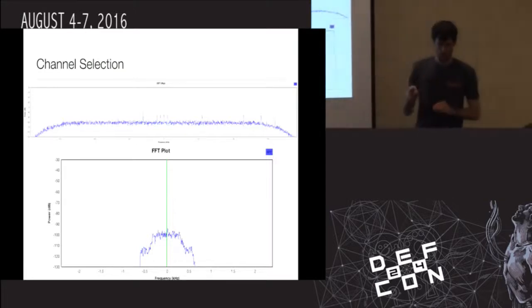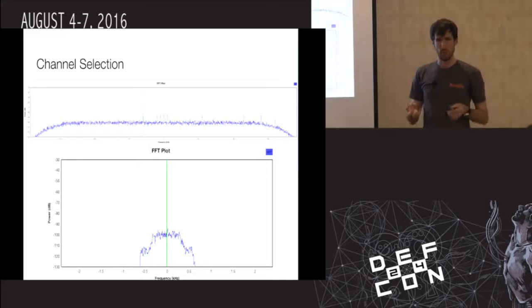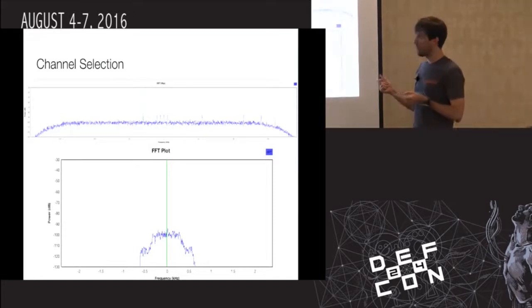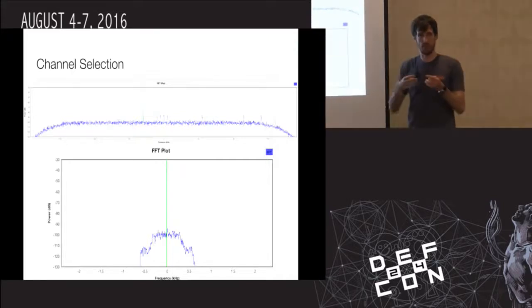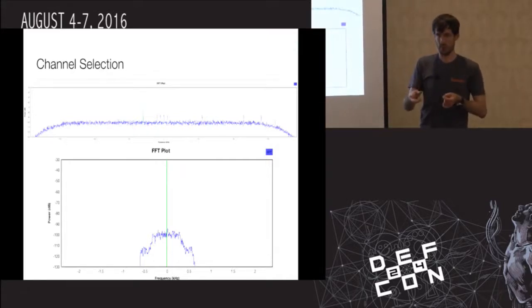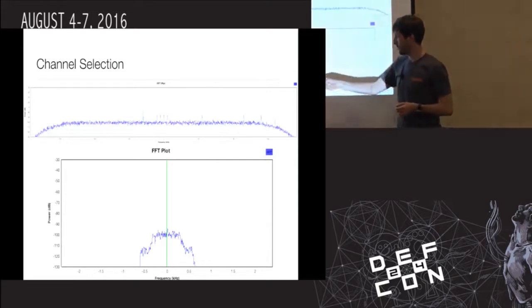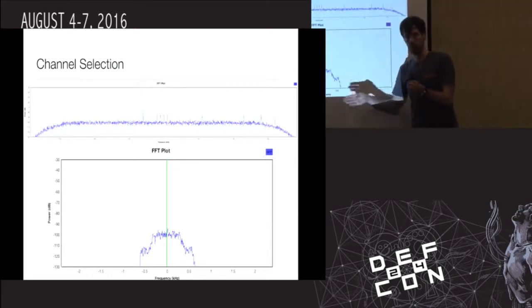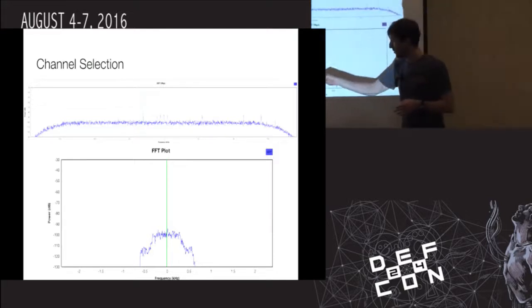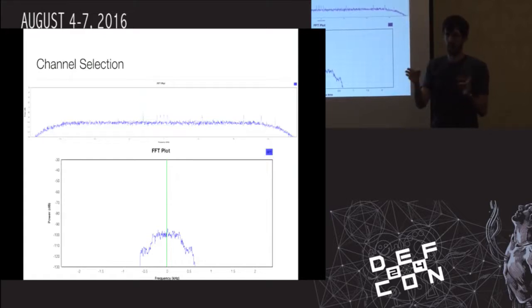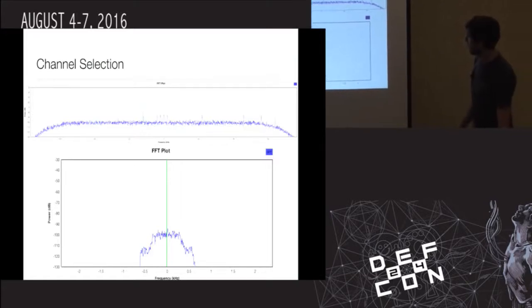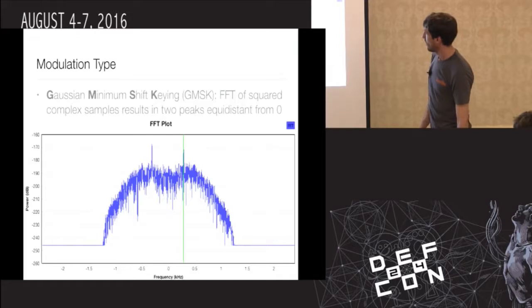But as you will see, one of the common things you have to deal with in a real-world radio system is clock drift. The oscillator that's originally being used to synthesize the signal is going to be drifting in relation to the synthesizer on your own SDR, which means that when you tune to the particular frequency you might know this is at, it might be offset. Or even if you manage to zero it down completely, it'll move back and forth, and that could be due to a whole bunch of different factors. But usually you want to implement some sort of scheme to keep a lock on it, and I'll show you how to do that.